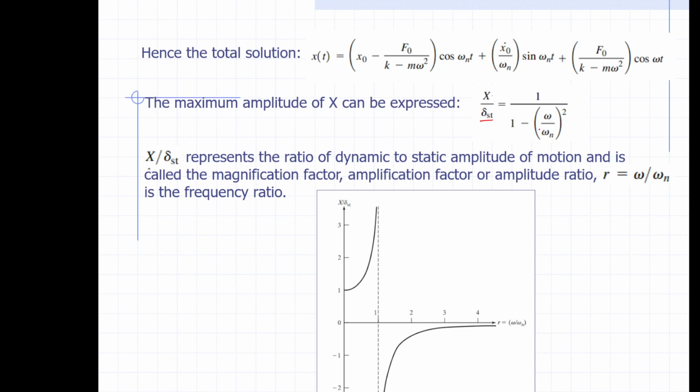Let's say you design a satellite that of course has a certain natural frequency. If the frequency of the vibration from the rocket is the same as the natural frequency of the satellite, maybe your satellite is broken before it is released from the rocket. See?